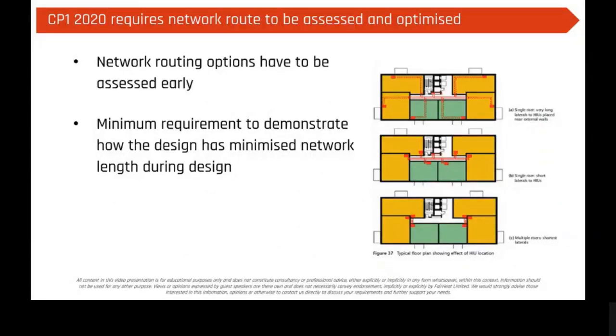But the big thing is, just by doubling up the riser, moving the riser location from the central location and splitting it to 2 locations, the amount of red pipe work per floor has dropped significantly. And all I've really added is, for a floor height of 3 meters, an extra 6 meters of pipe work compared to the single riser, because I've got a set of flow and returns. And this pipe work here would be closer to a total of like 20 to 30 meters per floor. So I'm saving a significant amount of pipe work. That reduces capex, but it also reduces losses.